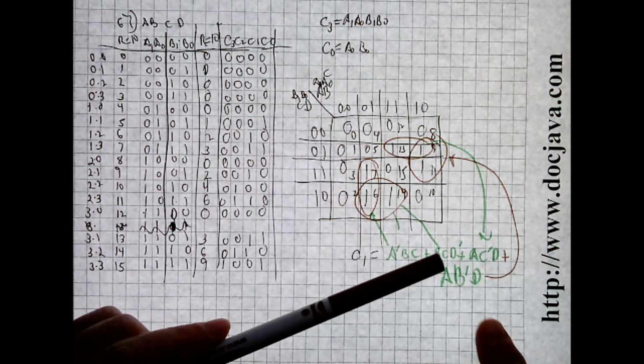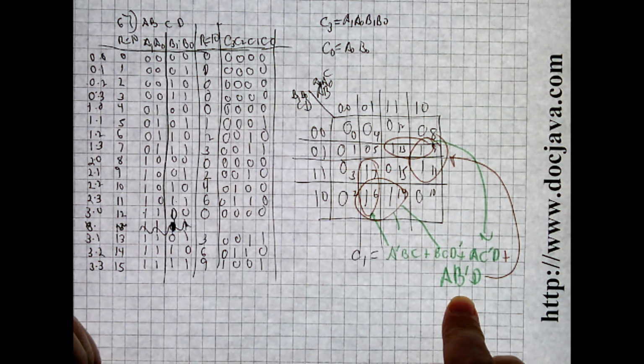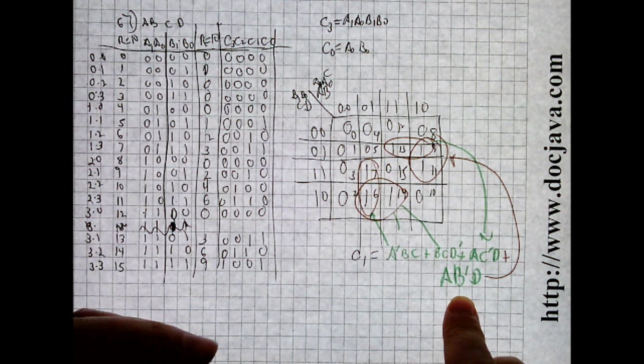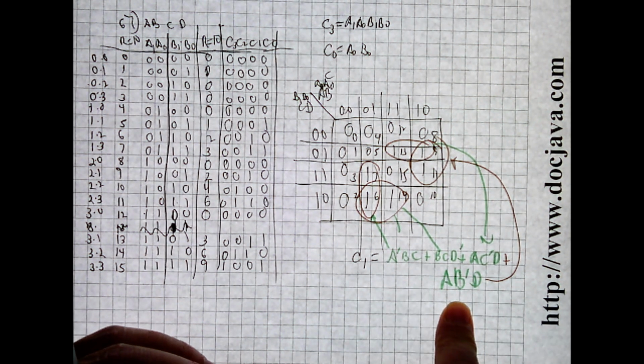So then you would look for this expression for C1 and see if you could get that from a simplified version of the schematic diagram. So basically you would have to redraw it and then annotate it, or print it and then annotate it, and that would give you an expression that's equivalent here. It would take a little time, but eventually you would find out that yes, indeed, what you have there is a 2 by 2 binary multiplier. And so that's the upshot of all of this.